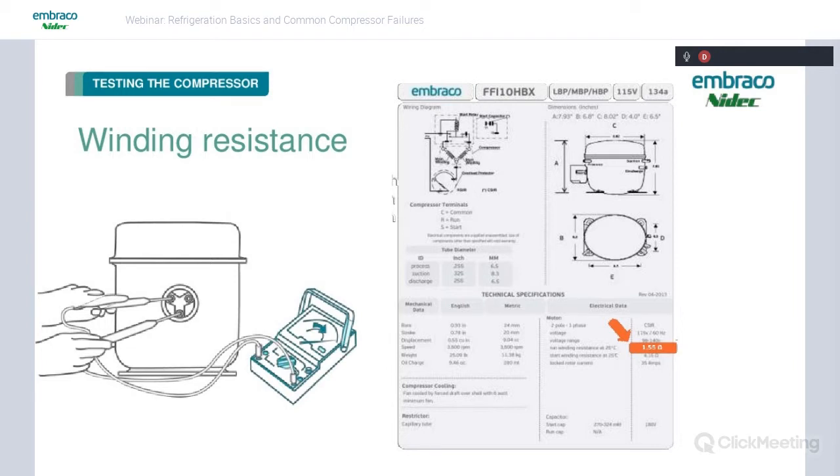If you have the ability to let that compressor cool off, maybe come back and check it and see if it's closer. It's very possible to have one that's showing a bit out of range, out of that percentage, but still be good because of temperature differences.